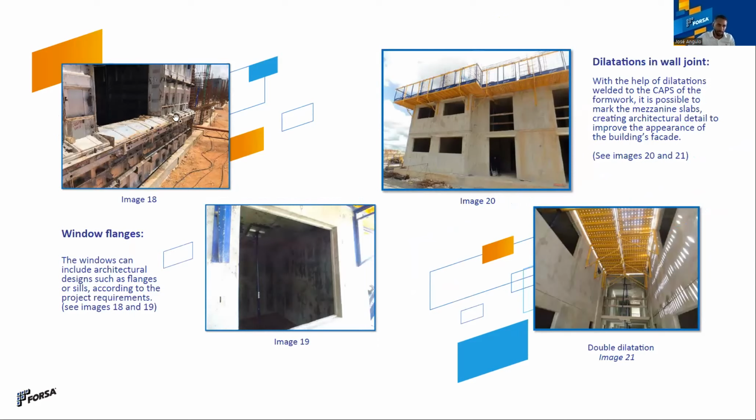For example, this one is the formwork for a special border detail. This one is located in the seal and helps to make these special window borders more beautiful, faster. Of course, the pouring normally had to be at a good speed, but here you have to check frequently with your vibrator in order to keep all the concrete in place. You know about the fluency, density, and all these factors that can help you to pour the concrete properly.